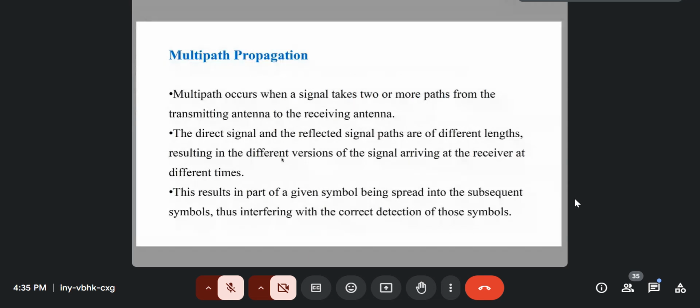When you carry pulses, the Fourier transform of the rectangular pulse is actually the sinc spectrum. Well, it's not the sinc waveform, it's the sinc spectrum. You have to be very careful. When you refer to the waveform, you're talking about the time domain. Spectrum, frequency domain.